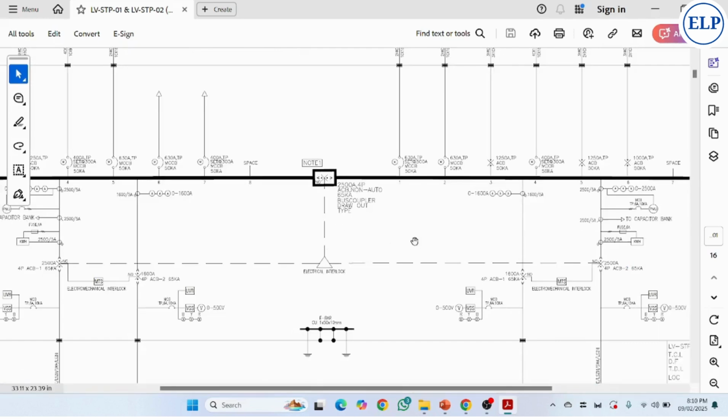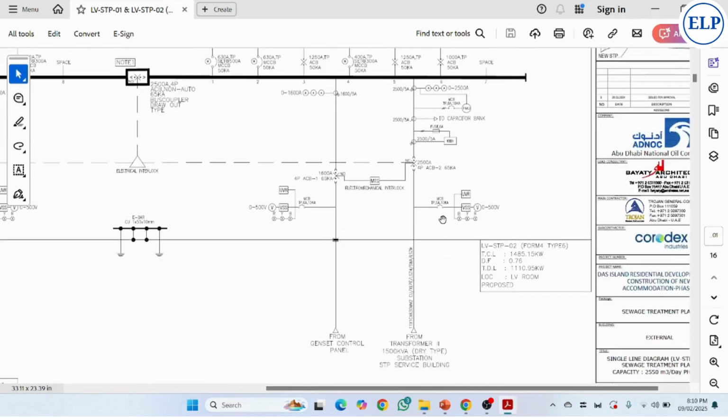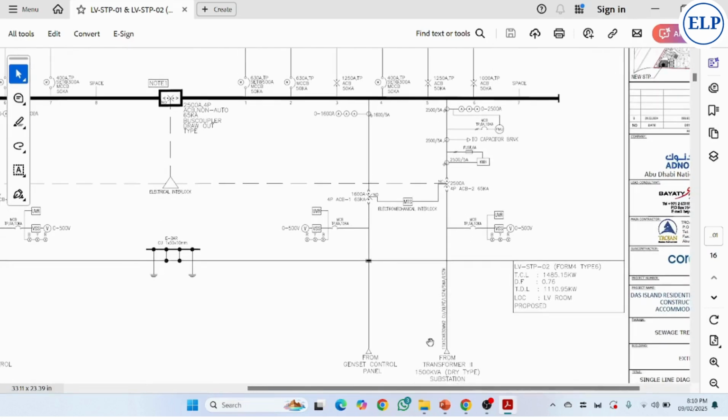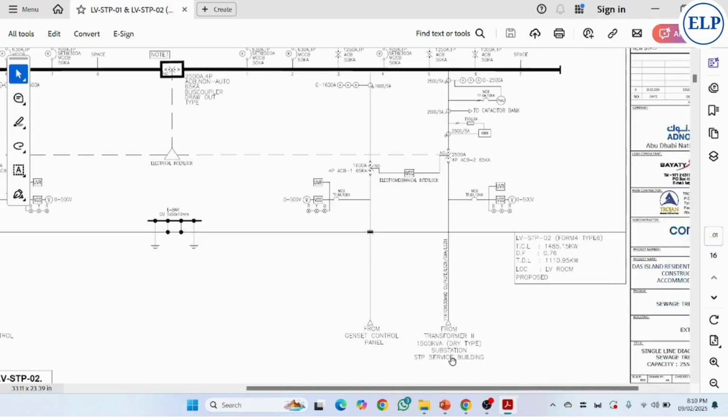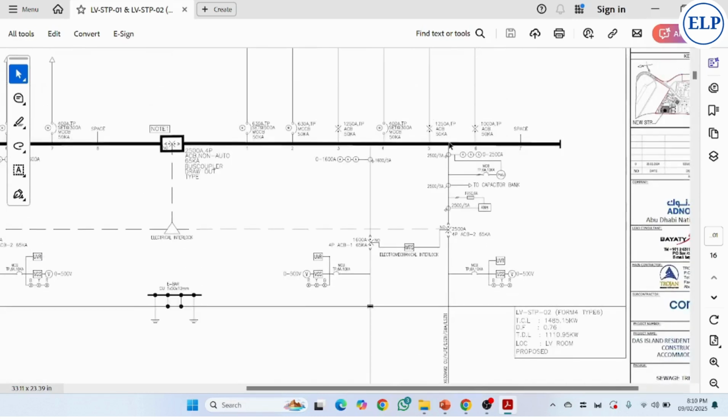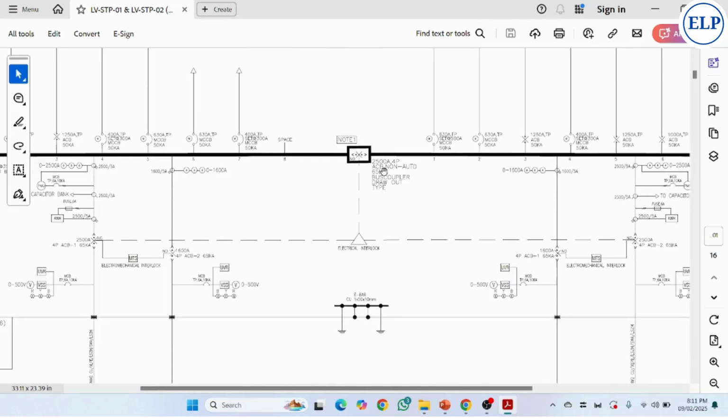This one-line diagram begins with the low voltage. Currently, there's a connection coming from one substation; let us consider this as a power grid connection. It will connect to one transformer, and further, by using one protective device, it will connect to one switchgear panel. Those identical names, type of design construction, how much connected load, demand factors, demand loads, where it should be located, those details are shown, along with any bus coupler connected to the switchgear panels, which we can call bus-to-bus couplers.